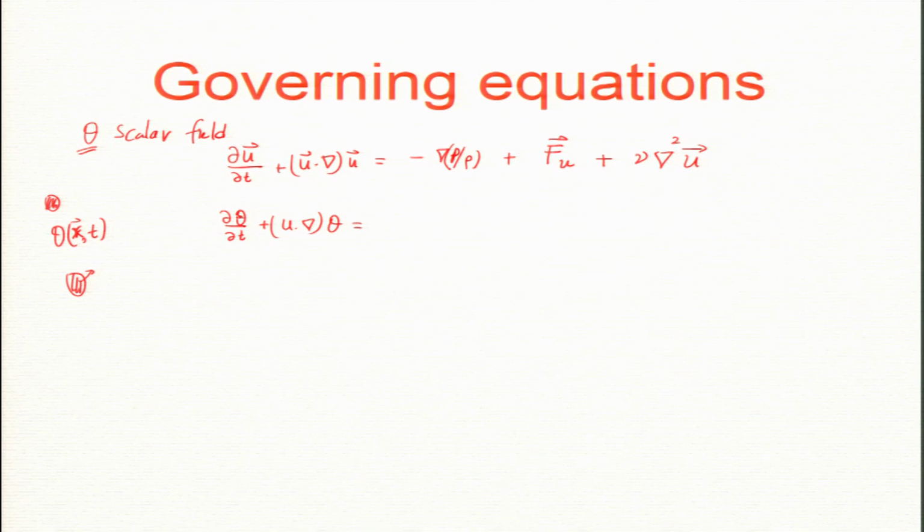This part is the total theta inside a small packet, and that can change by advection and by diffusion. It is changed by advection, the theta flux going out of the sphere, and then we have diffusion. Kappa is my diffusivity coefficient for theta.